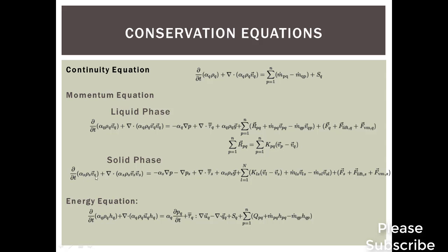When you come to the solid phase, there's an extra term, delta Ps. The delta Ps is the term which signifies the solids pressure, which may be due to kinetic energy, or due to an extra term like the interaction or coefficient of restitution, like two particles coming and colliding. That term is an extra amount of stress that is created, or an extra amount of pressure. In actual sense, it is the extra pressure being created due to these interactions.